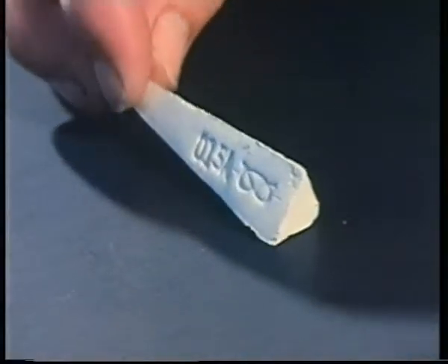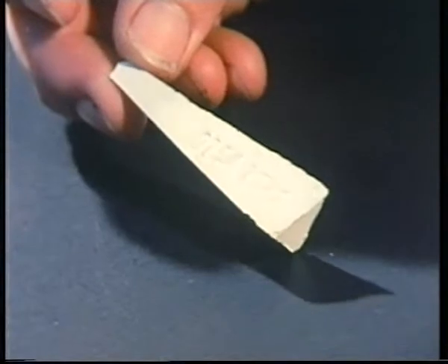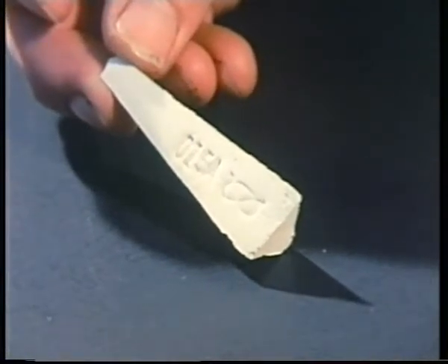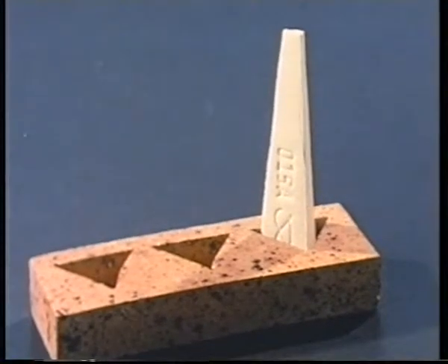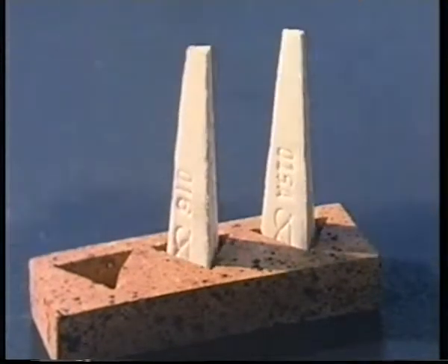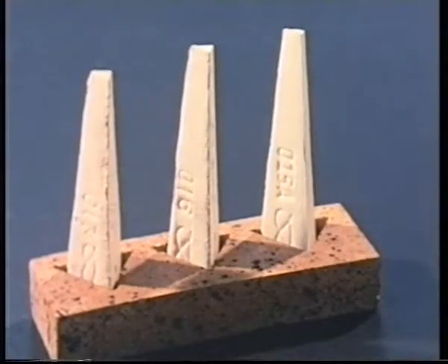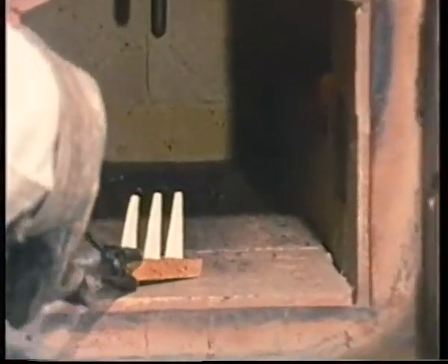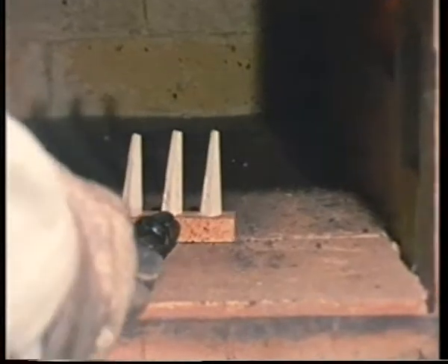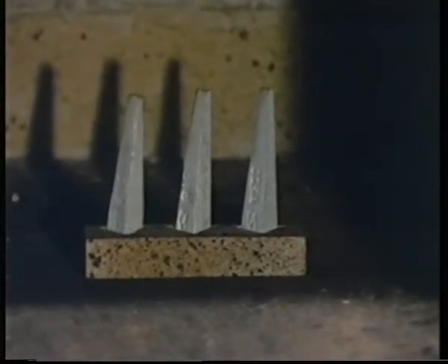This is a fusible cone. It's made from a special material which will cause the cone to collapse when it reaches a specified temperature. By varying the constituents, we can produce a series of cones which will collapse at different temperatures, in this case in steps of 5 degrees centigrade. We can use these cones to check the accuracy of other devices employed to measure temperature. For example, the thermocouple in this furnace. In the case of these 3 cones, the one in the middle is designed to collapse at 800 degrees centigrade. The other 2, 5 degrees above and below that temperature.